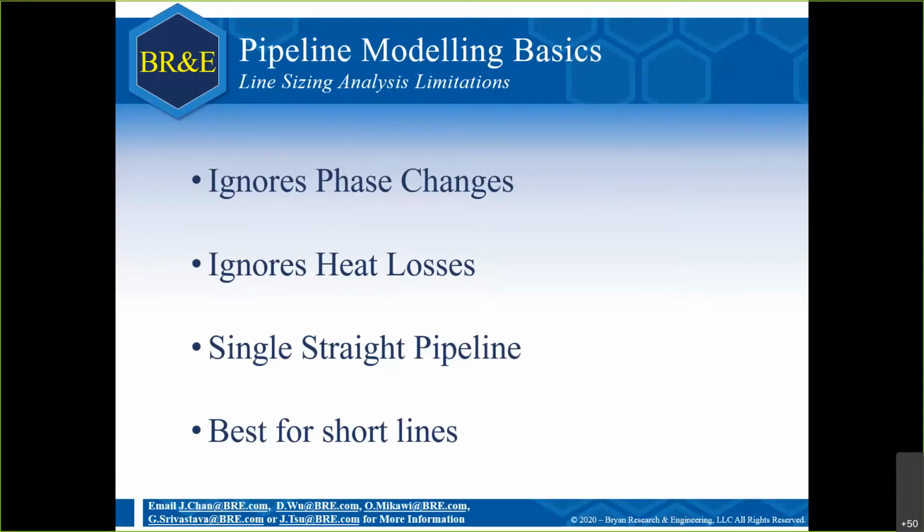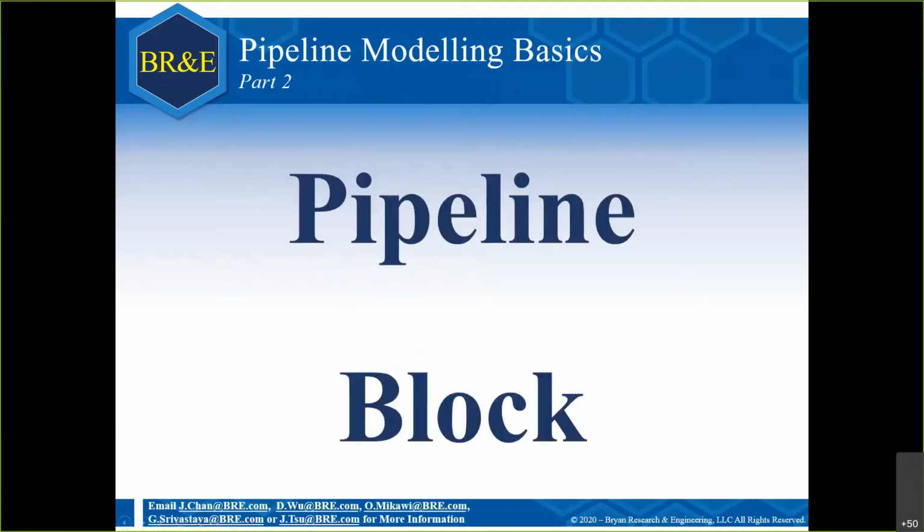If you put it in, you will see, okay, maybe I should start with 8-inch pipe and then work on from there. But of course, if you want to model longer pipelines, you will need a more detailed analysis, and that's where our pipeline block comes in. The pipeline block will allow for many, many more inputs, as well as generate a lot more meaningful results. It does this by rigorously modeling the phases at every interval.